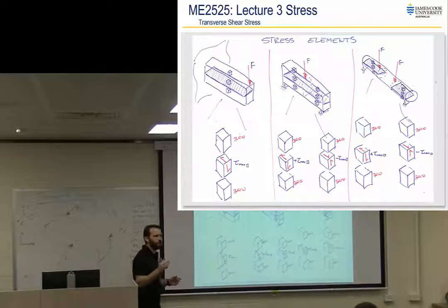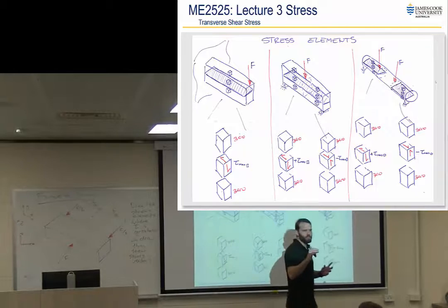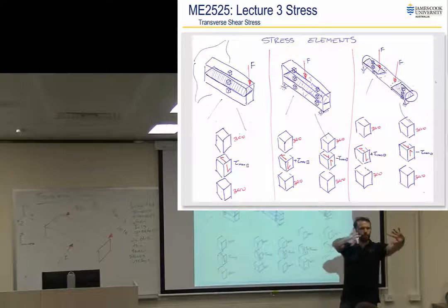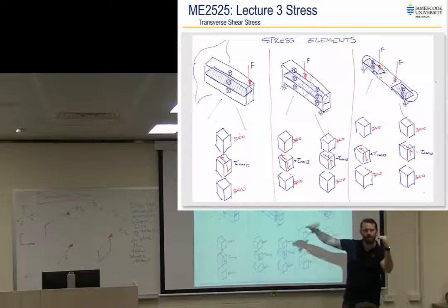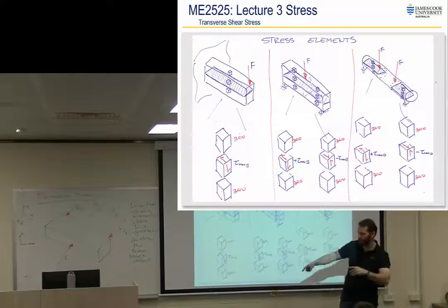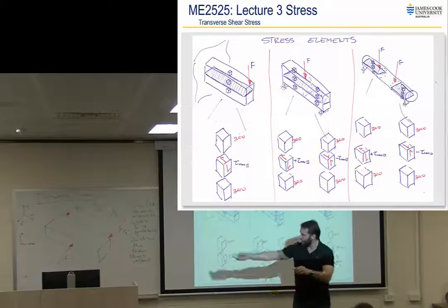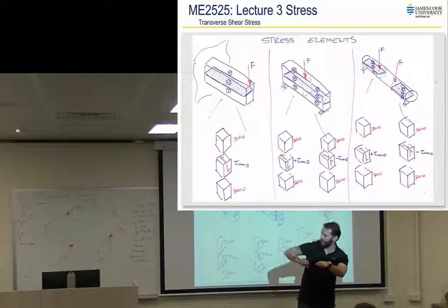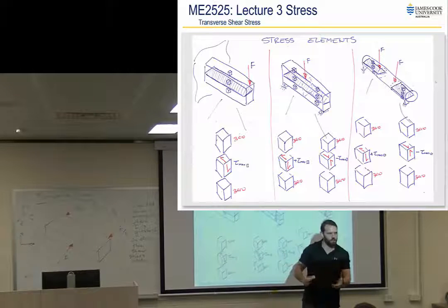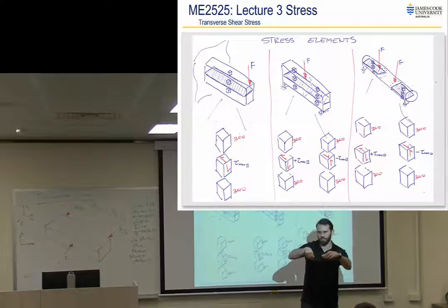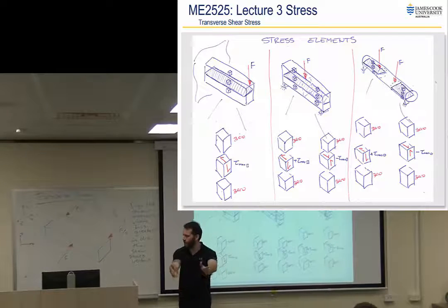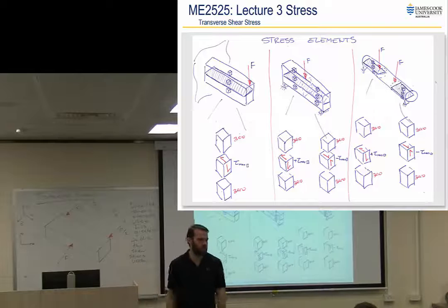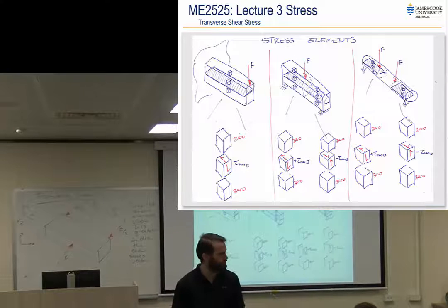The only thing will be is once you've got that value, you need to be able to look at your shear force diagram, treat it like a three-dimensional space and lay it back down to the way it needs to go if you want to do that positive and negative thing and get it right. Otherwise, you can just get your blocks and you can go, all right, I've got a force in the middle that does that. What direction do my vectors go on? You can actually do the interpretation in 3D space yourself without the shear force diagram. Up to you. Try both ways. It's good to have two different ways to do something.